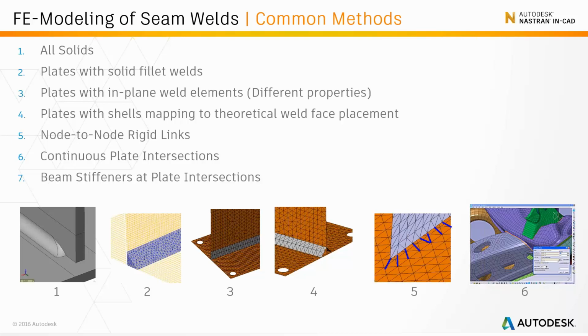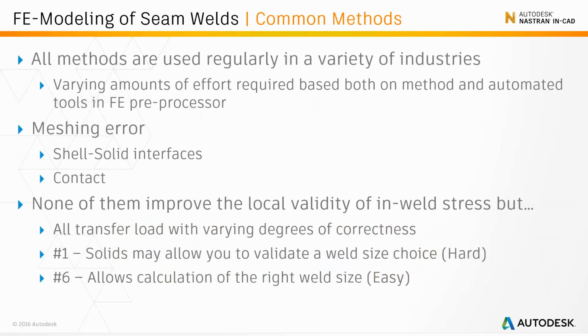Remember, in this instance, today we're predominantly focused on thin-walled sheet metal structures where the shell elements are most appropriate. We'll look at solid elements at the end of the webinar, but most of the focus is going to be around shell elements. So again, focusing on some of the common methods, some of these are harder than others. In some instances, some of them take much more time to make sure that the meshes line up, and thicknesses and nodal connectivity are where you want them.